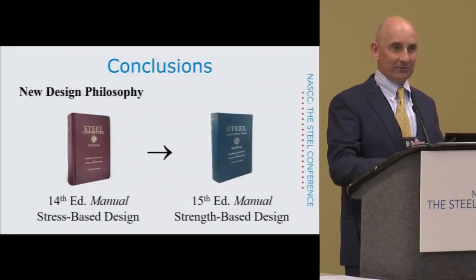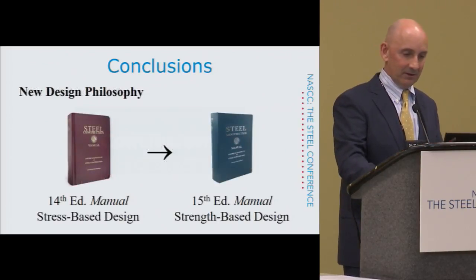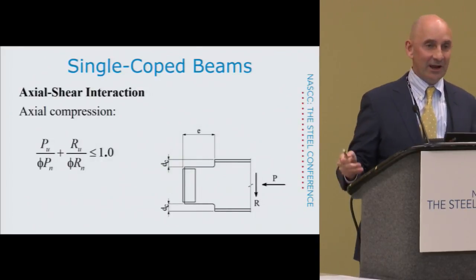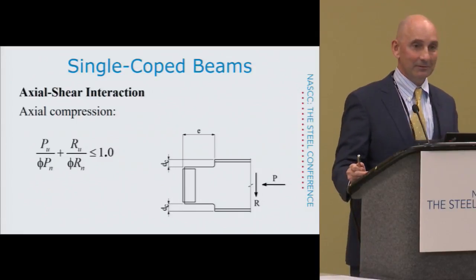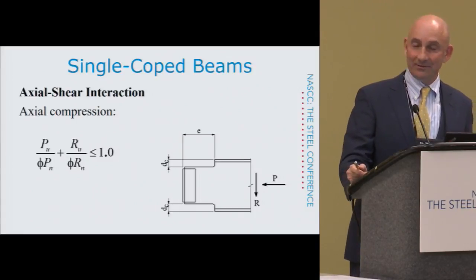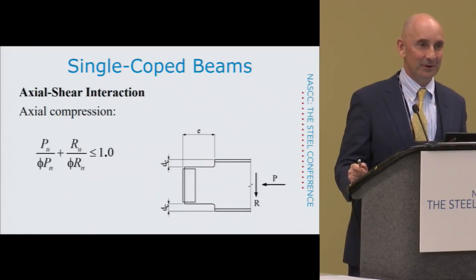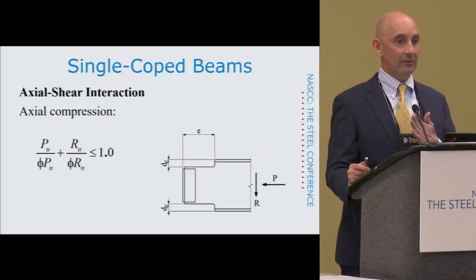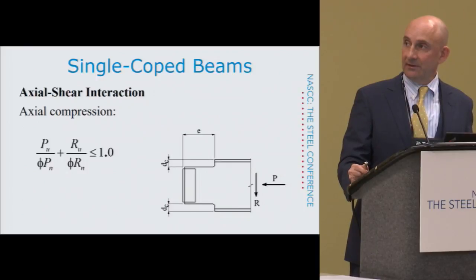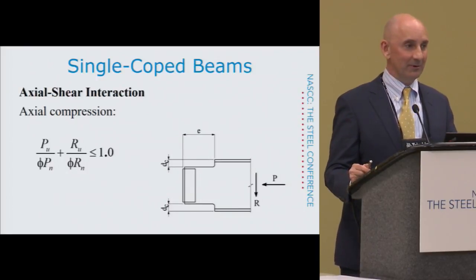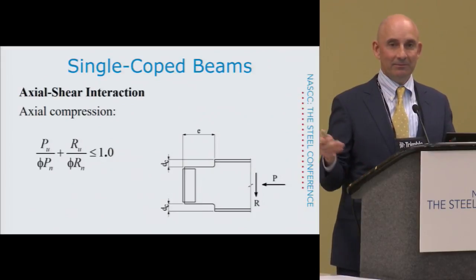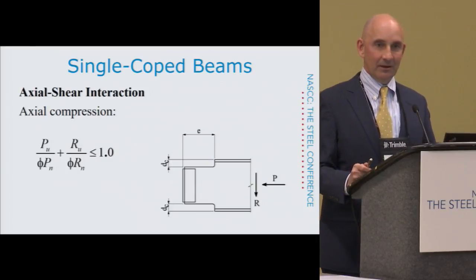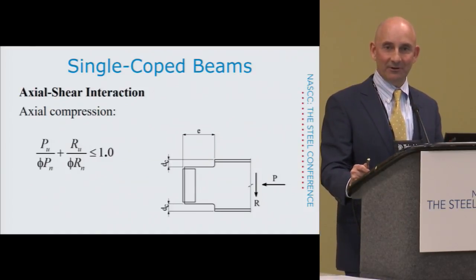In fact, take an extreme example. We have had this before, where we've used our judgment on real structures, where the clip angle has a giant axial load on it, so we had to use 8-inch clip angle legs, for example, and then maybe we might have a 6-inch cope. So the clip angles extend beyond the cope. In that case, if you've got, say, a 3/8 web and 3/4-inch thick clip angles, I'm not going to go through and calculate all of these buckling equations. I'll just use my judgment and say, we know that this is not going to buckle.